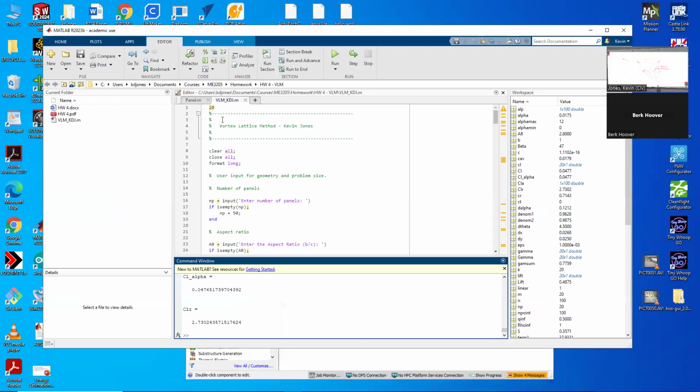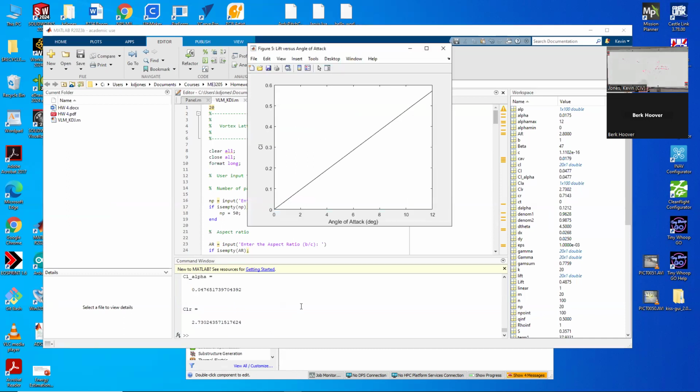Hopefully nobody threw away their codes. Hopefully everyone's codes are actually working. So let's see, I think it's 2.8 aspect ratio, taper ratio is 0. And then I think, what did I use? 40, I don't remember. You have to play around a little bit to figure out the sweep. A lot of you, I think, defined your sweep by leading edge, and the leading edge should be 55 degrees. I did mine with quarter chord, and in this problem, that's actually hard. I guess I could do the math externally and figure it out.